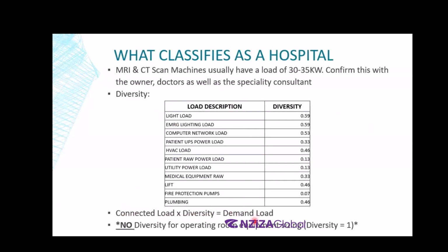Is the demand load concept clear? Or do you want me to explain it again? Are you guys sure? Please, some feedback. I can explain it to you again. So let's say this particular projector over here. The projector consumes, let's say, a total of 1000 watt. But do you think the projector is going to run every day of the year, 24 hours? No, right? So there is a diversity to its use. It is not going to consume 1000 watt all the time, right?